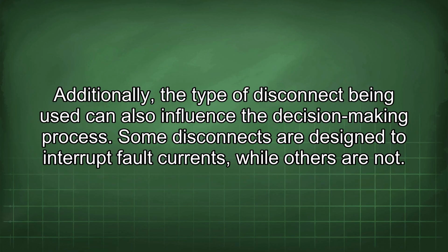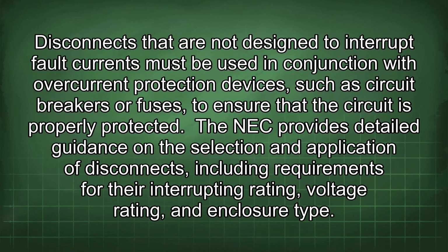Additionally, the type of disconnect being used can also influence the decision-making process. Some disconnects are designed to interrupt fault currents, while others are not. Disconnects that are not designed to interrupt fault currents must be used in conjunction with overcurrent protection devices, such as circuit breakers or fuses, to ensure that the circuit is properly protected.